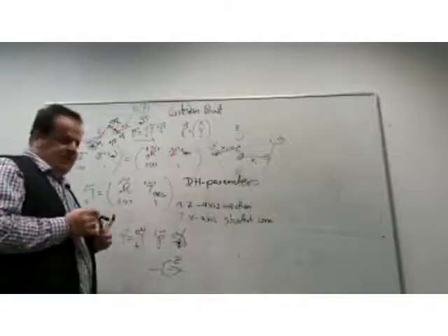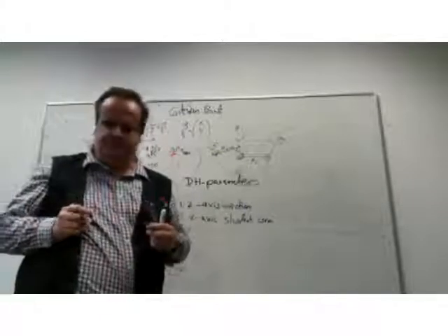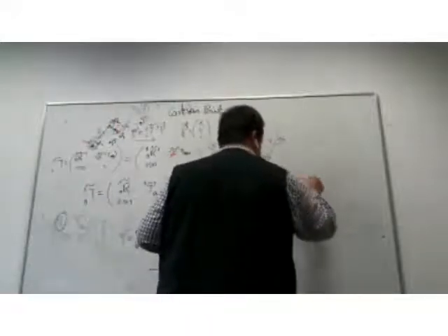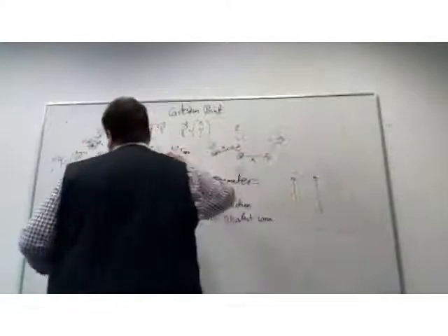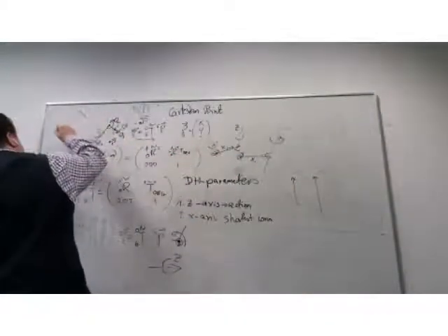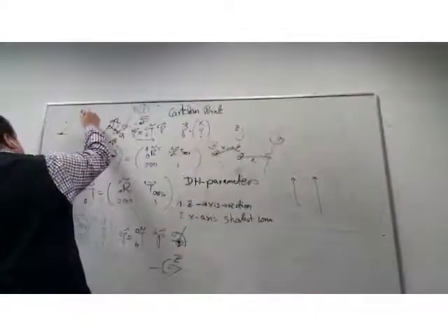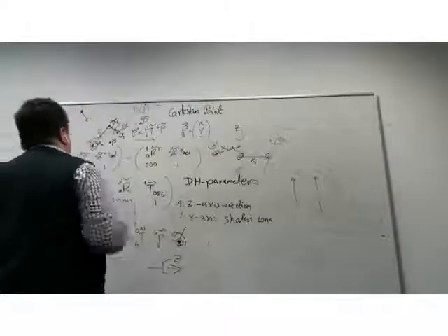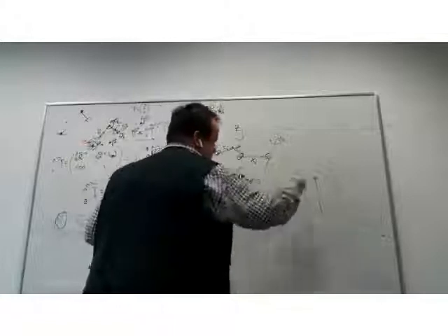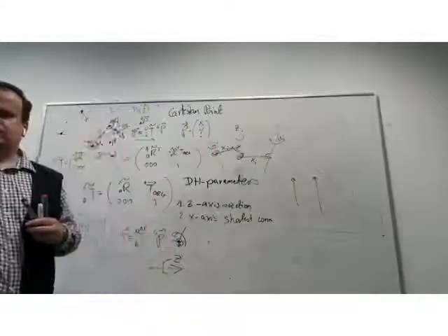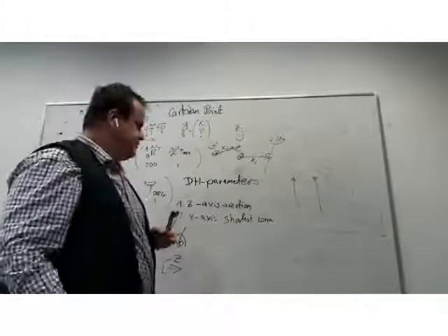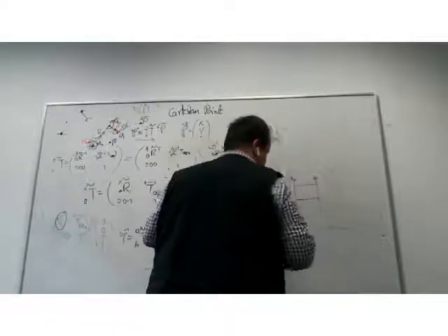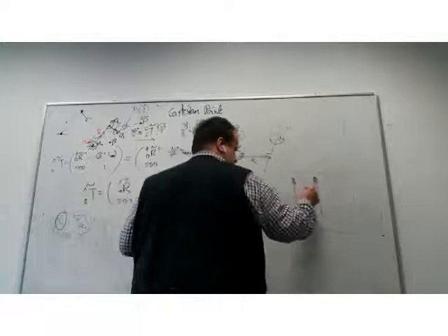Well, there are special cases. What are the special cases? The first special case, which is pretty common to the robot I'm drawing here: look at the robot. This is the z-axis pointing out. This is a z-axis pointing out. I have two parallel axes in this case. For this special case, I'm really free in the choice where I place my x.